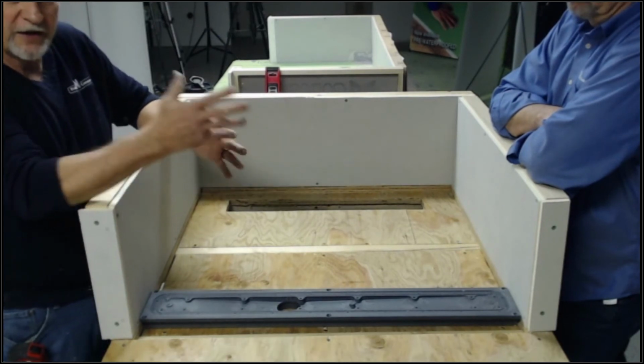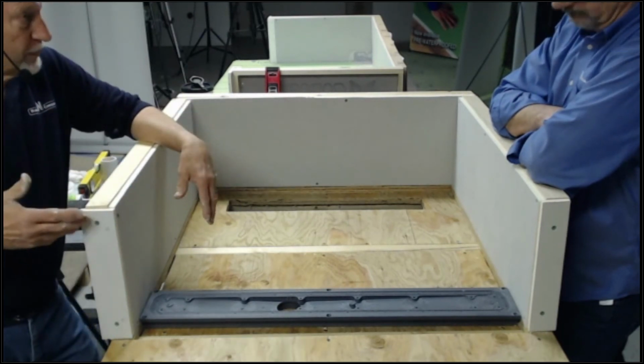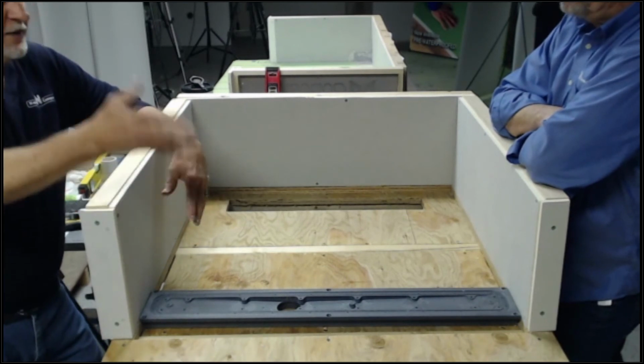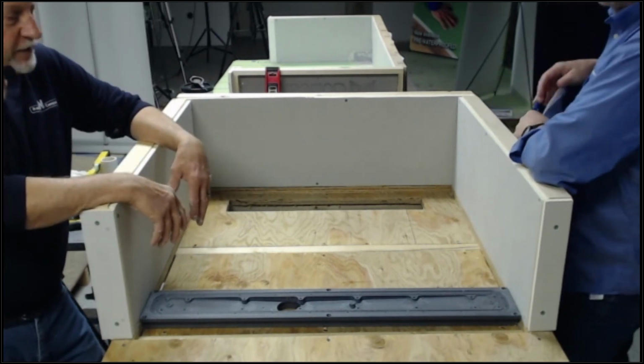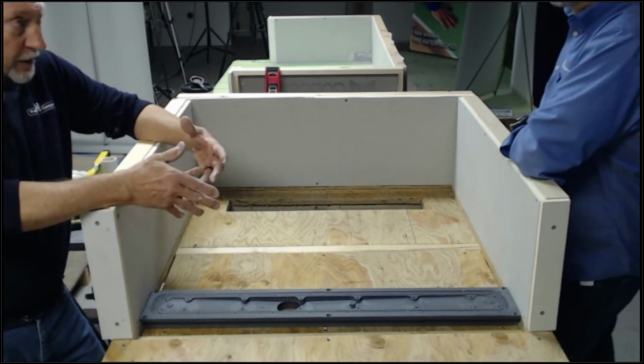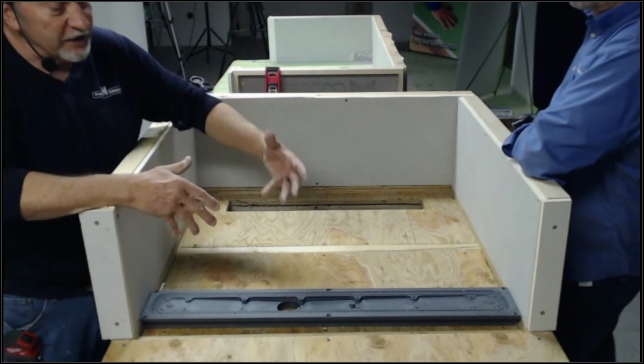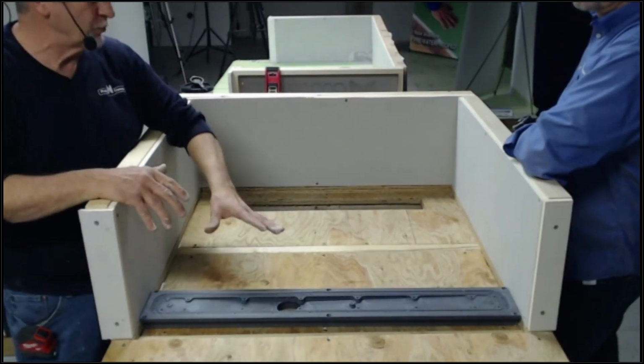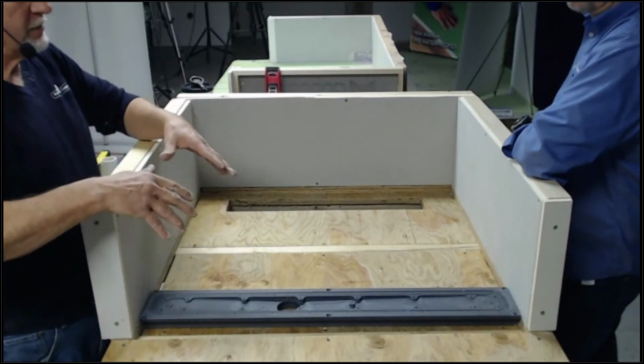First of all, you've got to have a 1/4 inch per foot pre-slope. You're taking up height. Then you're going to put a pan liner on that, and then a mortar bed on top of that. Typically you want 1.5 inches of mortar bed. So that doesn't work well with a 3/4 inch depression here. You almost double the overall thickness.